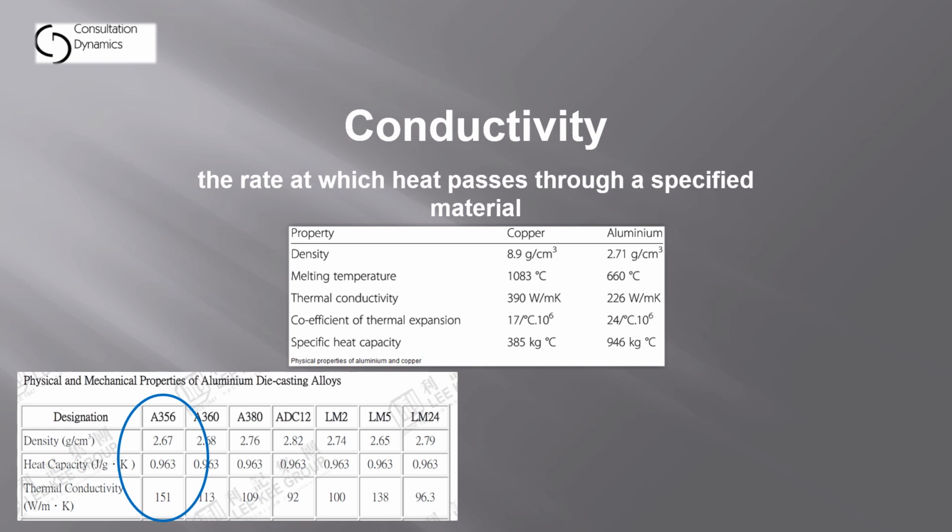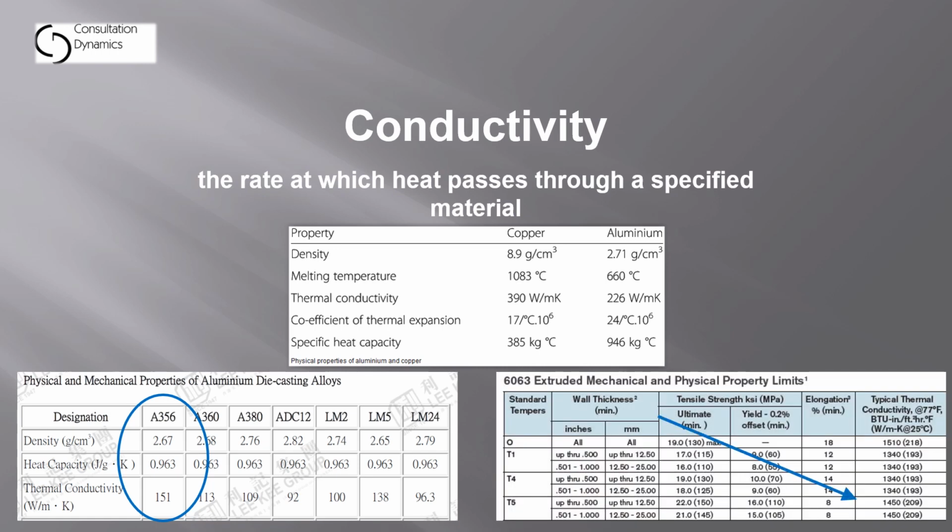die-cast fixture. What we do at US Architectural is we use some die castings and some sand or permanent mold castings, some high pressure, some low pressure casting processes, but in all of our heat sinks, where the optical elements are concerned and mounting components for getting heat away from the LEDs, all of this is done using the A356 material because of its superior thermal conductivity in aluminum. And we also use, in some instances, extrusions, which are an even denser form of aluminum alloy and therefore a little bit more thermally conductive.